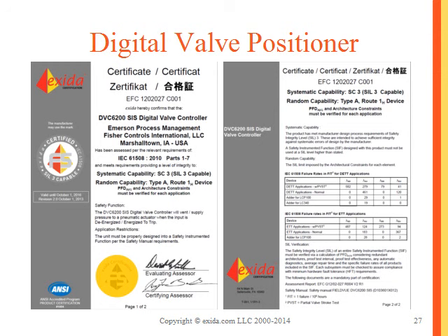Now, as I mentioned before, for final elements, we tend to list two sets of failure rates: normal failures, meaning the product is only used for, let's say, on-off, and then with partial stroking failures, where every now and then you perform a partial stroke of the device. The definition of a partial stroke, as to how much percentage closure you want to achieve, is all defined in the assessment report.